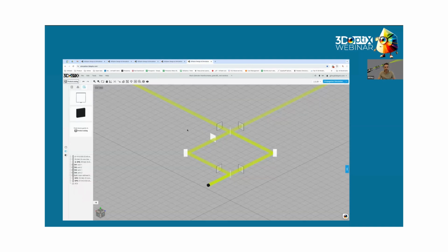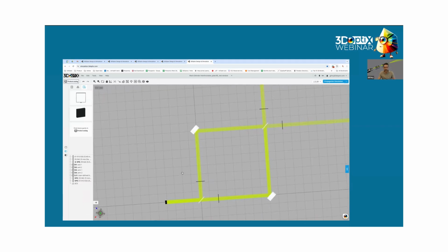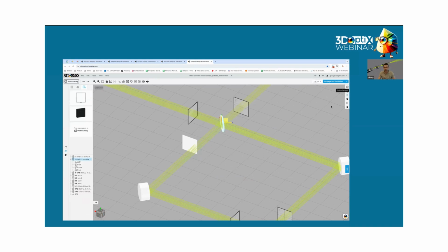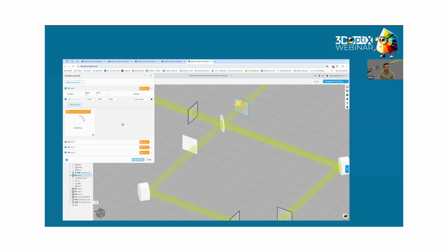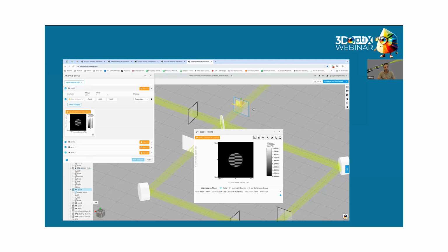My last example, this is a Mach-Zehnder interferometer. I want to show you coherence. So we designed here a Mach-Zehnder with two identical arms. And we have here a beam splitter, 50-50. And let's open this up. And I would get the result. So we developed and created this window, and we're talking about this detector. And you can see here that the fringes fall a half a pi.